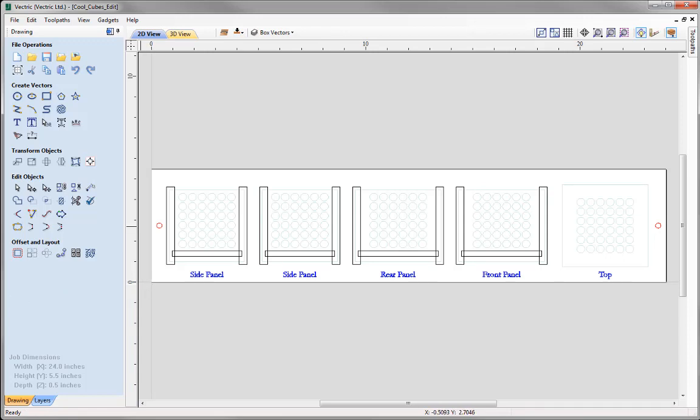So now I want to run through how I plan to cut the whole part. Now in terms of machining, I plan to cut these vectors using the pocket toolpath so that we can assemble all of the panels to form the box. Then I'm going to take these vectors here, and we're going to machine the dowel holes all the way through the material and into the spoil board. And that is all of the toolpaths that are required for the top side.